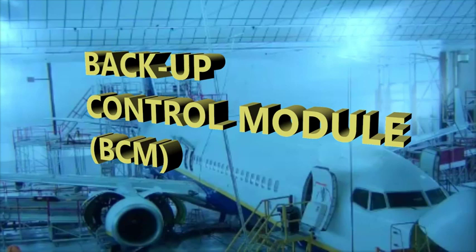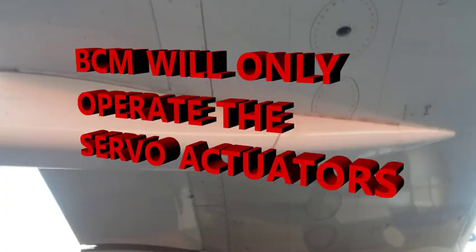There's also a flight control backup control module. The backup control module that I just mentioned is going to only operate the servo actuators and not the EHAs. Your EHA being your electrohydrostatic actuators, and also your electric backup hydraulic actuators. Those are not going to be run by that backup control module. There's another module that does that. That's the EM, your electronic module. And the backup control module, like I said before, if you had a total loss of all the computers, that's going to be the one that takes over.